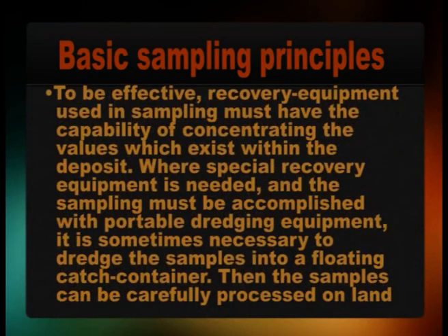Next is to be effective. Recovery equipment used in sampling must have the capability of concentrating the values which exist within the deposit. Where special recovery equipment is needed and the sampling must be accomplished with portable dredging equipment, it is sometimes necessary to dredge the samples into a floating catch container. Then the samples can be carefully processed on land.